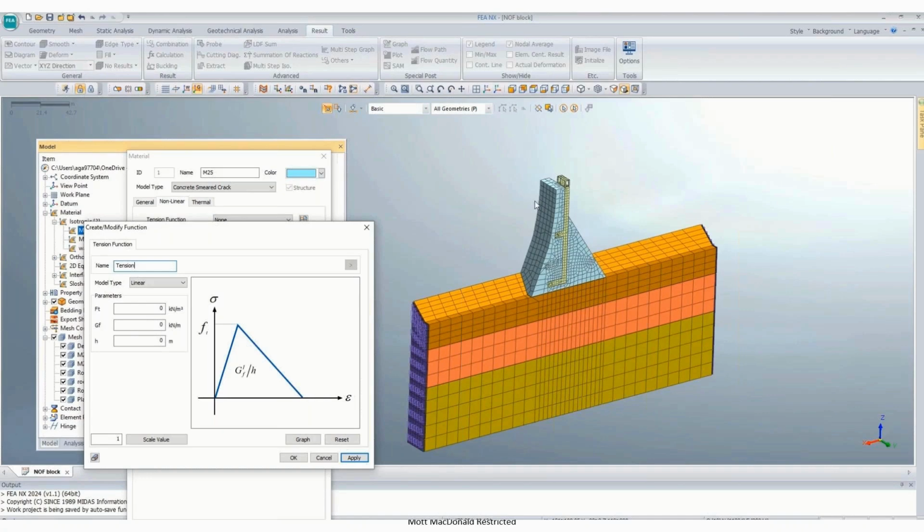So for numerical analysis, we can't consider zero tensile strength of concrete. That criterion is applicable for evaluating reinforcement as per the bending theories, limit state method or working stress method. There, the assumption is that concrete will not take any tension, and the entire tension will be taken by the reinforcement. Here we don't have reinforcement. Concrete will have some tensile strength.